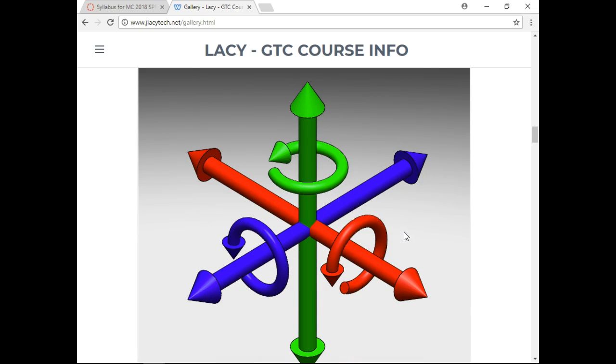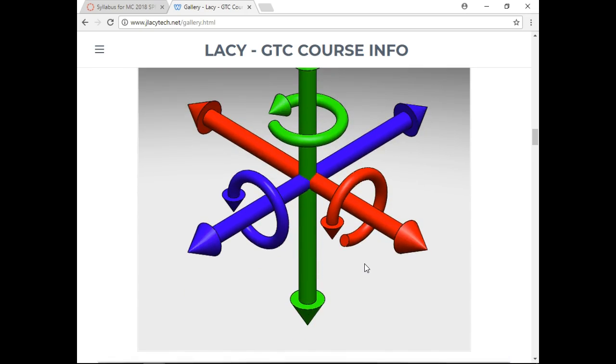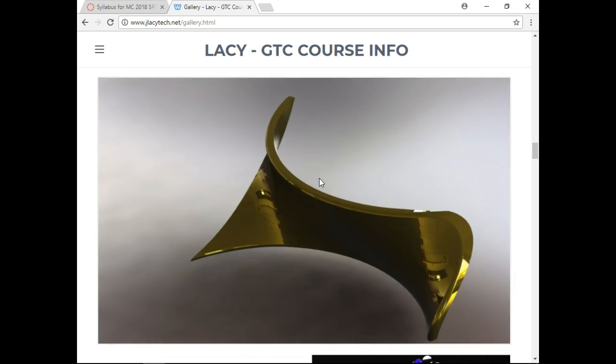Our 6 degrees of freedom. When we get over to the assemblies, you have movement in X, in Y, and in Z, and then rotation about each of the axes. So those are our constraints when we're dealing with the assemblies. If it's a static assembly, all of those will be constrained. If it's dynamic, then one or more will be allowed to maintain its motion, maintain its movement.